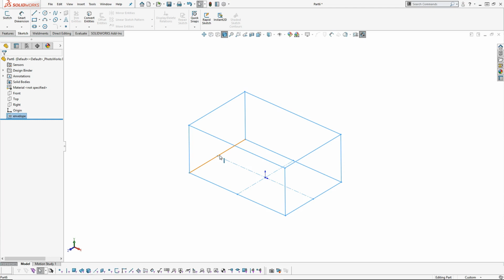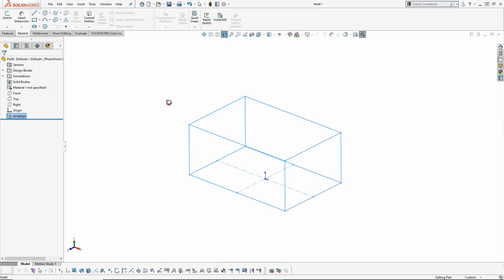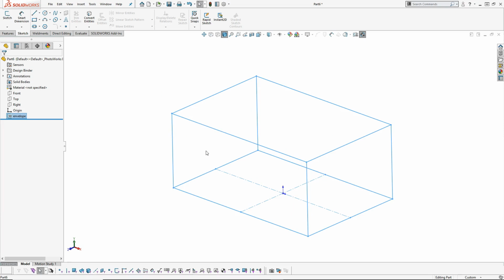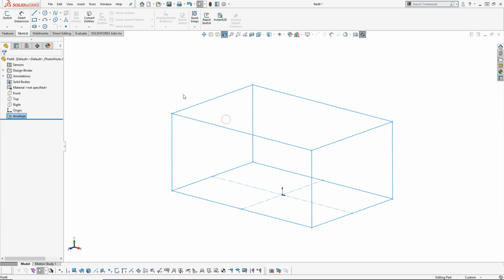I built this to my desired size, and the consideration is interior, exterior. Are we going to be able to cut that material exactly 16 by 36, exactly 16 by 24, or are we going to have to give it a little bit of fluff? So the design is in its perfect state when we start thinking about how this is structurally going to work and what kind of dimensions we put on it. We're in the weldment sheet metal world where we can put some decent tolerances on it, but we're not going to be getting real crazy with it.